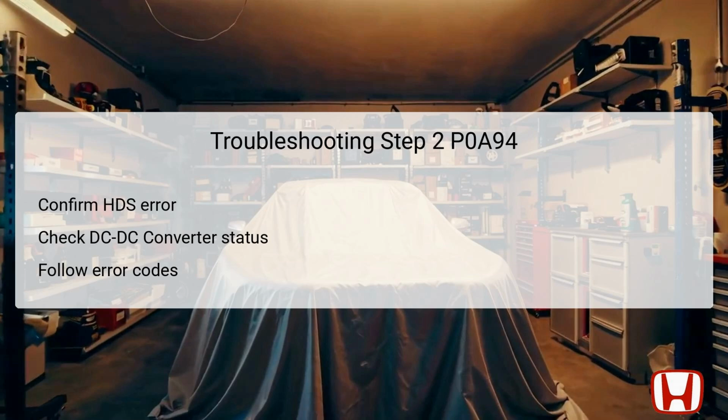The HDS provides a clear and systematic approach for identifying whether the converter is malfunctioning or operating normally. By cross-referencing these error codes with the initial findings from the test drive, technicians can gain a more comprehensive understanding of whether the DTC is indeed due to a failing DC-DC converter or another system component.